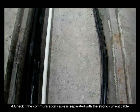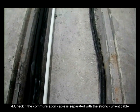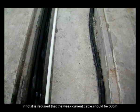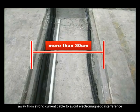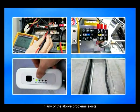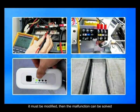4. Check if the communication cable is separated from the strong current cable. If not, it is required that the weak current cable should be 30 centimeters away from the strong current cable to avoid electromagnetic interference. If any of the above problems exist, it must be modified. Then the malfunction can be solved. If not, please go to the next step.